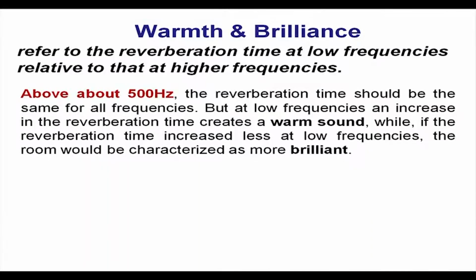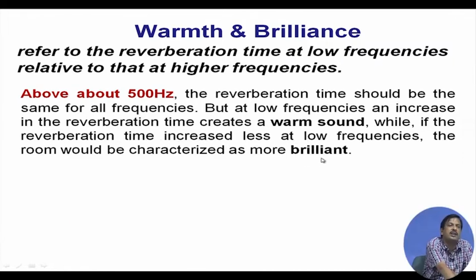Then this parameter refers to the reverberation time at low frequency relative to that at higher frequency. Above 500 Hz, the reverberation time should be small for all frequencies, but at low frequency an increase in the reverberation time creates a warm sound, while if the increase is less at low frequency, it creates a brilliant sound. So, this is the definition of warmth and brilliance.